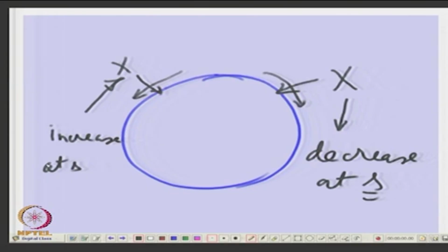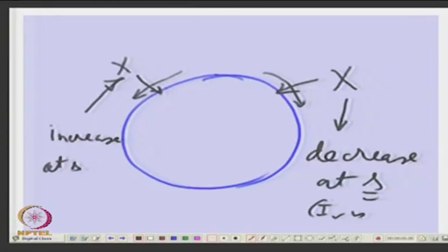Compared to x, because I can't be every time asking the question and giving the answer myself. Why is it so? I said as it starts running, rotor MMF would decrease compared to when it was at start, because rotor current will decrease, isn't it? See, if it was carrying say 10 amperes at start, it will carry 9 amperes at some speed, because IR is less.